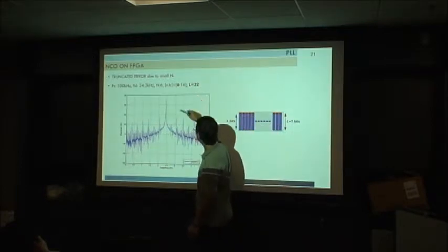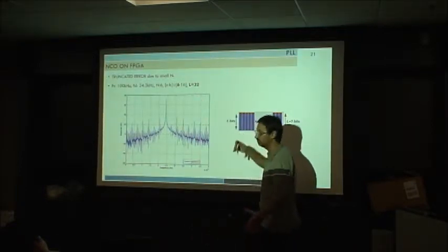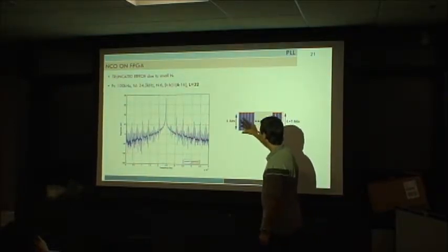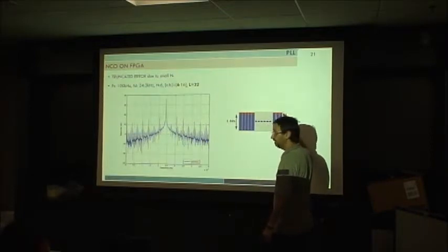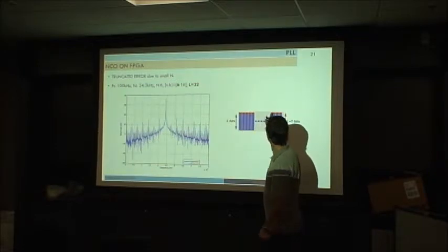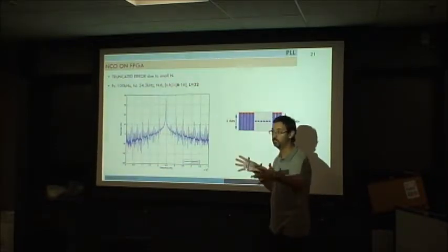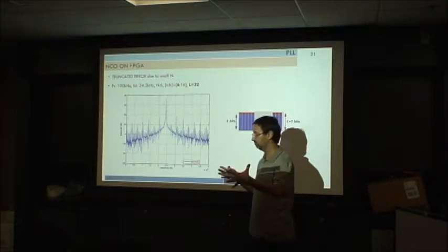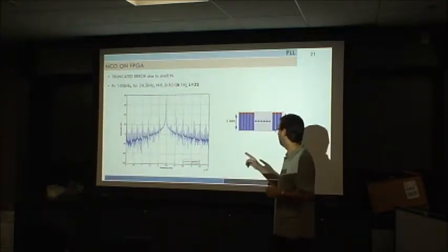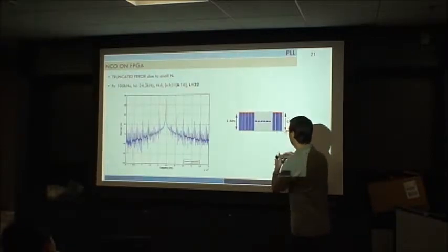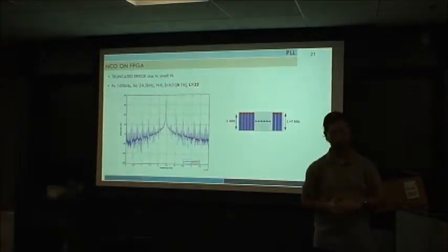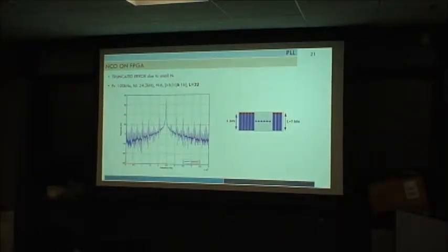And the L, this number is 52, which is quite big. But taking into account that this is the memory that we have, if we increase one bit here, the resource increases n times 1. That's fine. But if we increase 1 bit on n, we will double this size. So make sure what you are increasing.